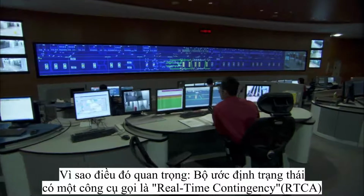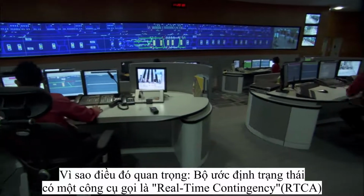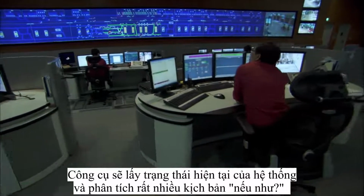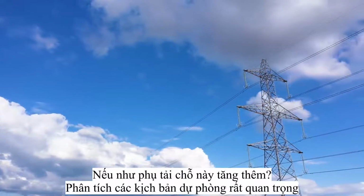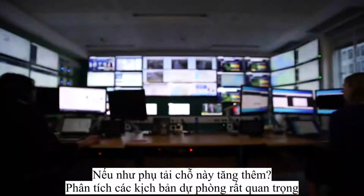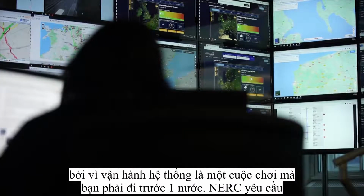Here's why that matters. The state estimator feeds into another tool called a real-time contingency analysis, or RTCA, that takes the estimated state and does a variety of what-ifs. What would happen if this generator tripped? What would happen if this transmission line went offline? What would happen if the load increased over here? Contingency analysis is critical because you have to stay ahead of the game when operating the grid.